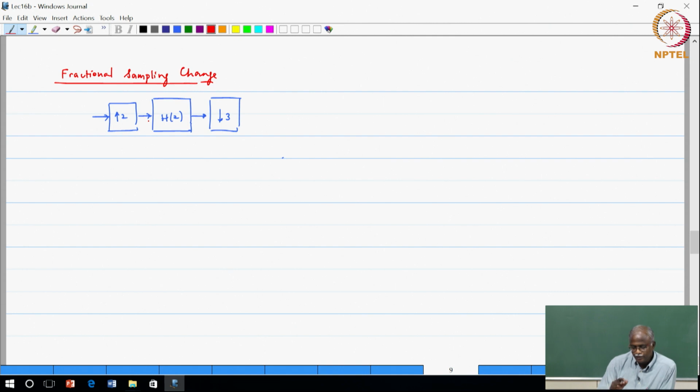So now observation number 1. I know that if I do polyphase decomposition, I will get a factor of reduction in terms of computational complexity. If I combine it with this side, I will get a 3x complexity reduction, because that is what I get when I do the polyphase decomposition, and then I do that. Of course, if I do it this way, I will get a 2x, right. Now the question is, I am a little bit greedy, I want 6x.